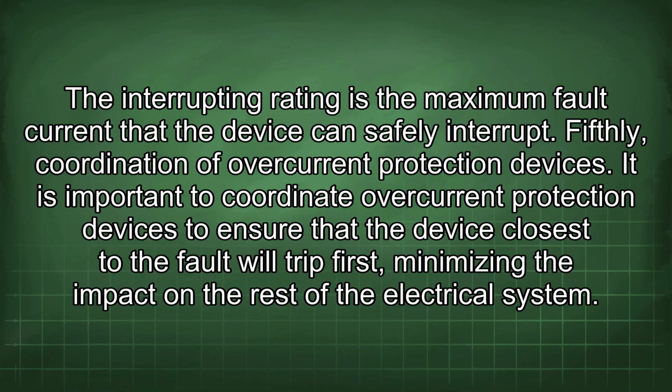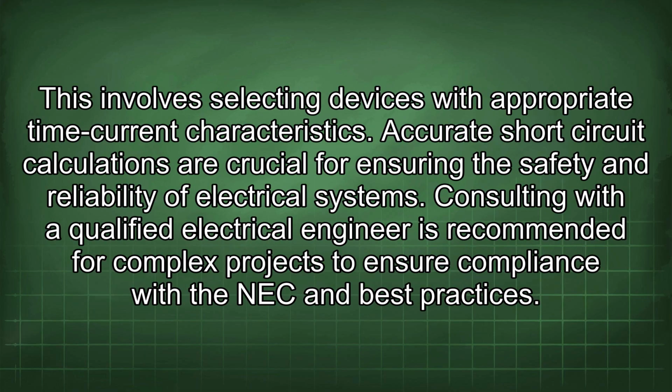Fifthly, coordination of overcurrent protection devices. It is important to coordinate overcurrent protection devices to ensure that the device closest to the fault will trip first, minimizing the impact on the rest of the electrical system. This involves selecting devices with appropriate time current characteristics. Accurate short-circuit calculations are crucial for ensuring the safety and reliability of electrical systems. Consulting with a qualified electrical engineer is recommended for complex projects to ensure compliance with the NEC and best practices.